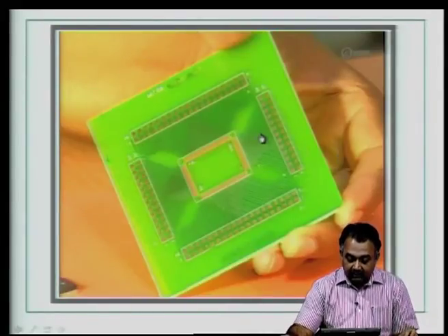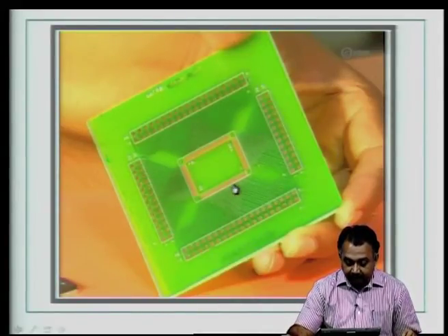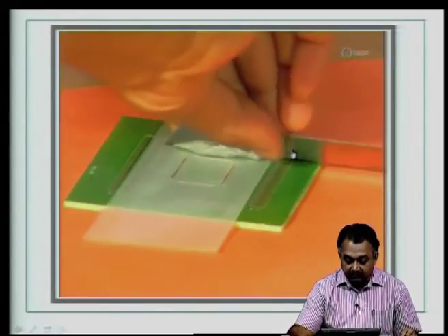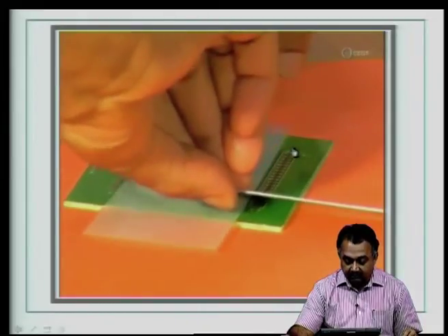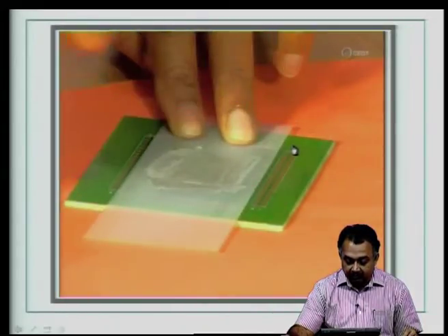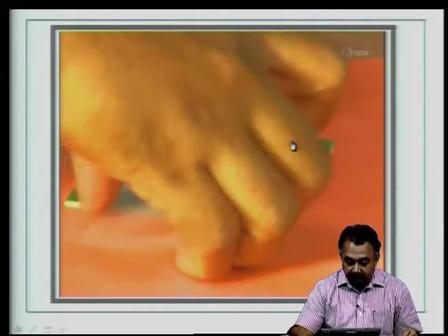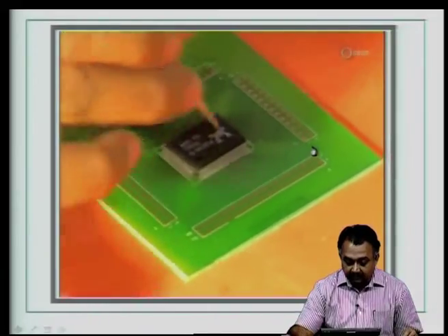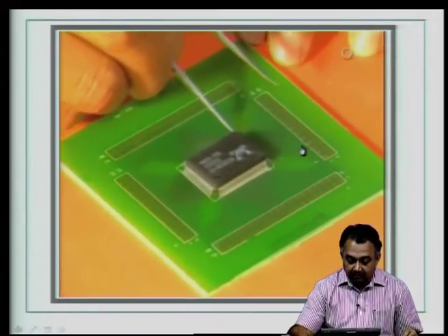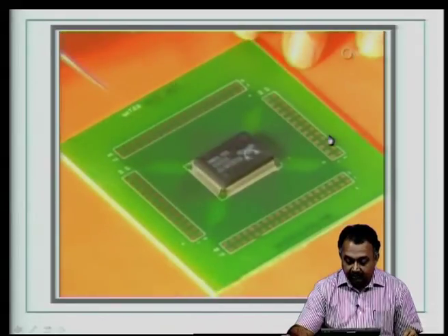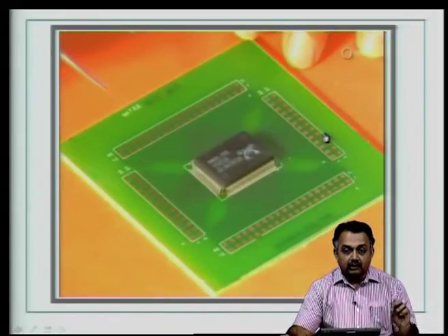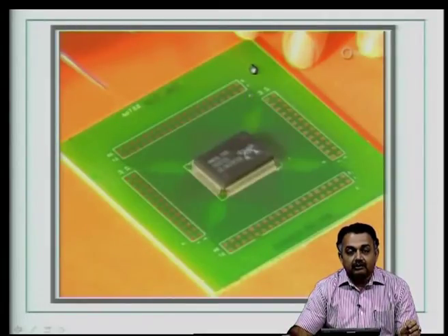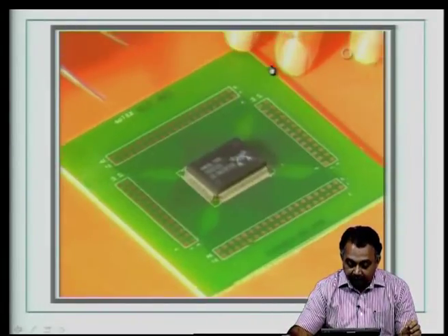Now, for this again you have the footprint ready, you have the test points ready. Now, you start dispensing the solder paste using a stencil. Very thin material is used as the stencil base. You can now see that the solder paste is dispensed. You are now using your manual method of alignment and trying to make sure that to the maximum possible you can do a good alignment before reflow.